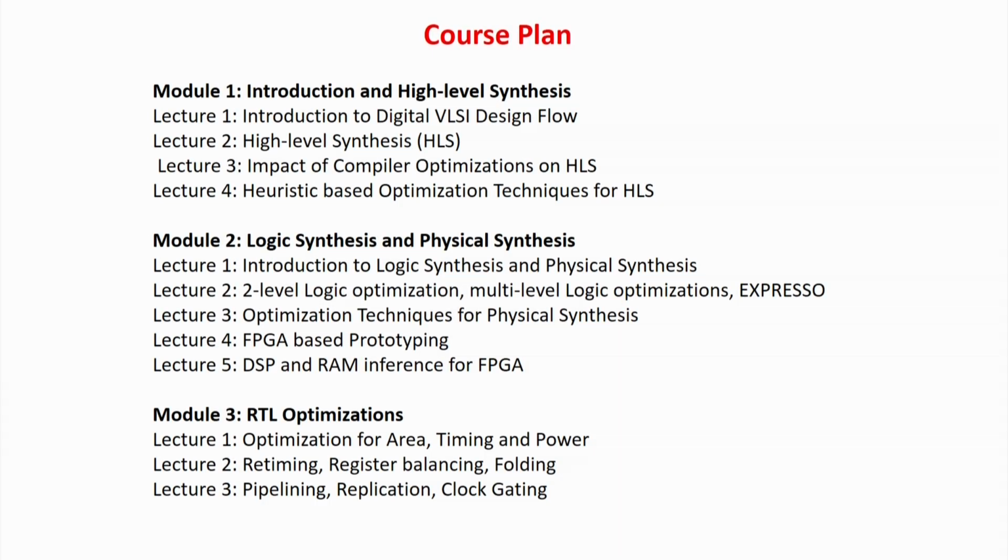In module 2 we'll discuss logic synthesis and physical synthesis. We'll discuss two-level optimization, multi-level optimization, and heuristic optimization like Espresso. We'll talk about physical synthesis steps like placement, floor planning and routing, briefly. But what we're going to discuss more is FPGA prototyping, right? As you mentioned, when you design a big processor, first it is prototyped on FPGA, to check whether things are working for say a week or so, and then it goes for final ASIC fabrication, right?